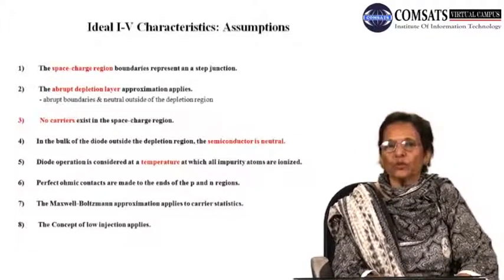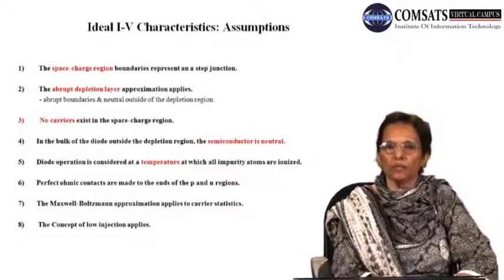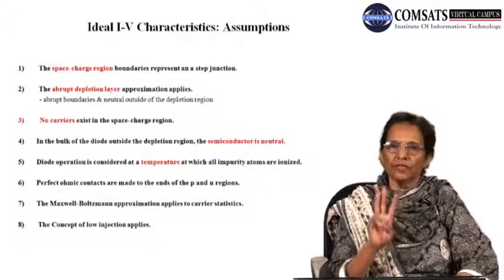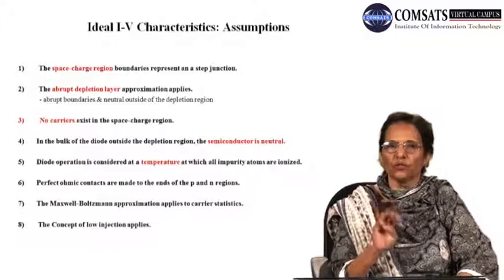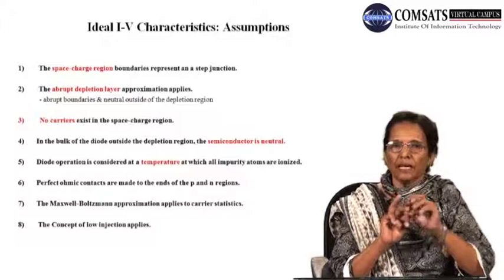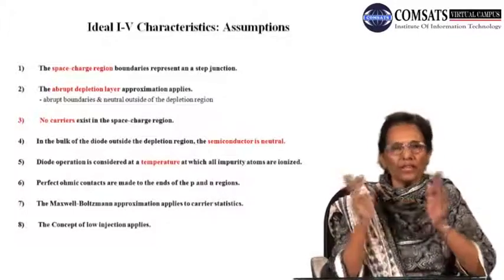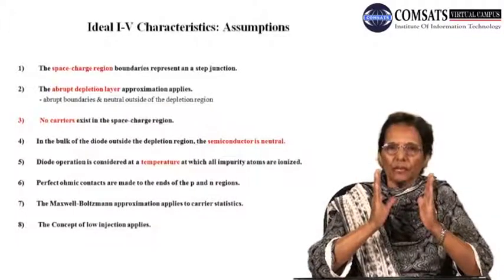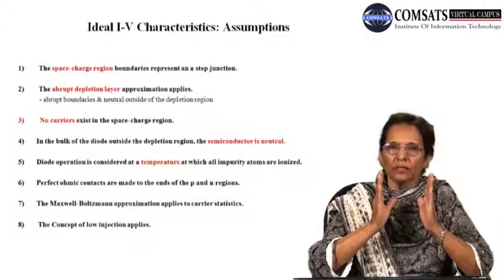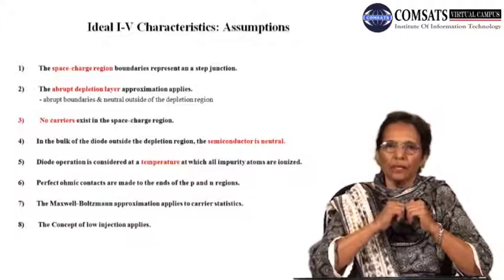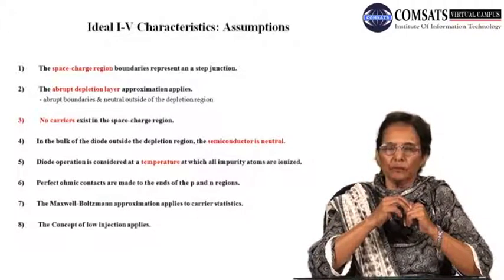And finally, because I mentioned that we will be talking about the state of the PN junction or diode under 3 different conditions of biasing: no bias, which is the equilibrium state, forward bias, and reverse bias. Now, as we mentioned in lecture number 4, when a forward bias is applied across a PN junction, what is a forward bias? The positive terminal of the battery applies potential across the p-type region, and the negative terminal of the applied bias is connected to the n-type region.